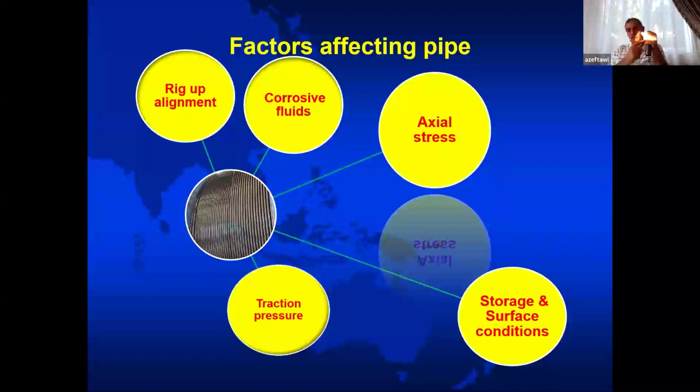If the pressure you are putting is low, this will create slippage, or might let the well pressure push this pipe outside, which is again a slippage. The slippage is created by either the pipe weight or upward, the well pressure pushing the pipe up. If you are putting too much pressure on the traction, this creates fatigue to the pipe itself and affects its pipe life.